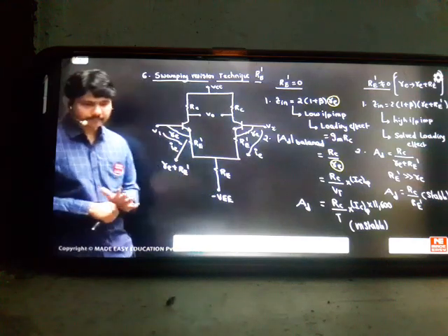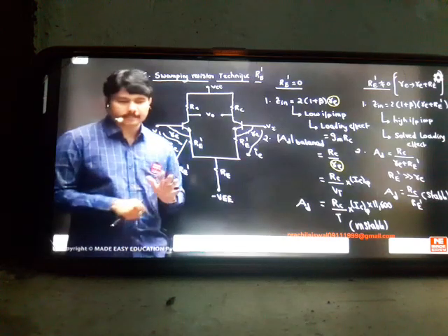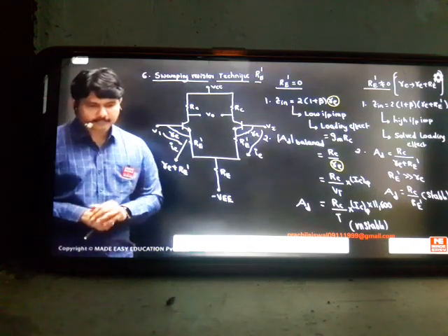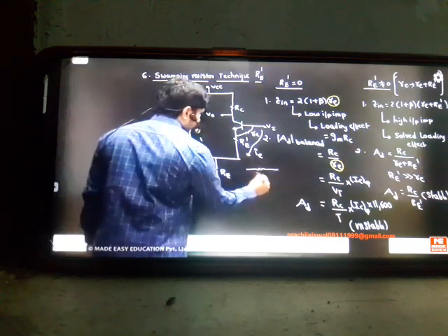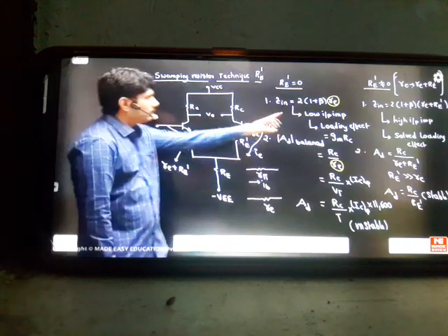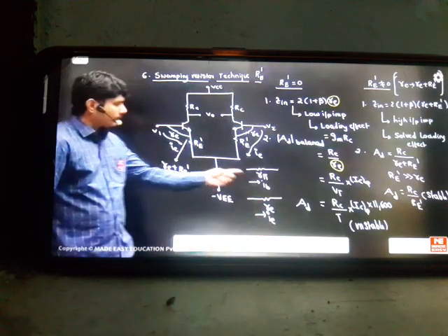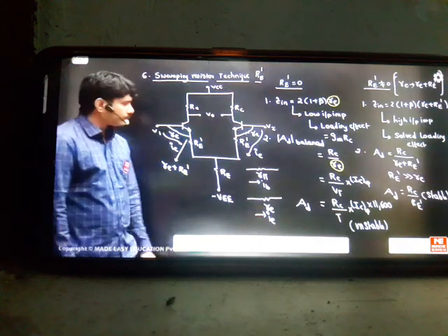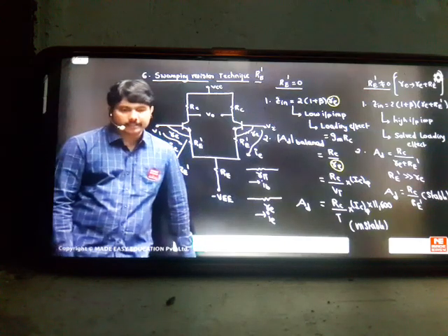Great, Kamlesh. With this we have finished the swapping techniques, how to increase the input impedance. Stabilizers, don't get worried about these techniques. If anybody wants R pi to be written, it should be with the IB current. Whenever you want the RE effect, for RE write the IE current. So you can convert whatever you want. If it is the IB current, it is R pi. You can interchange whenever you want. Here I am showing it for RE.